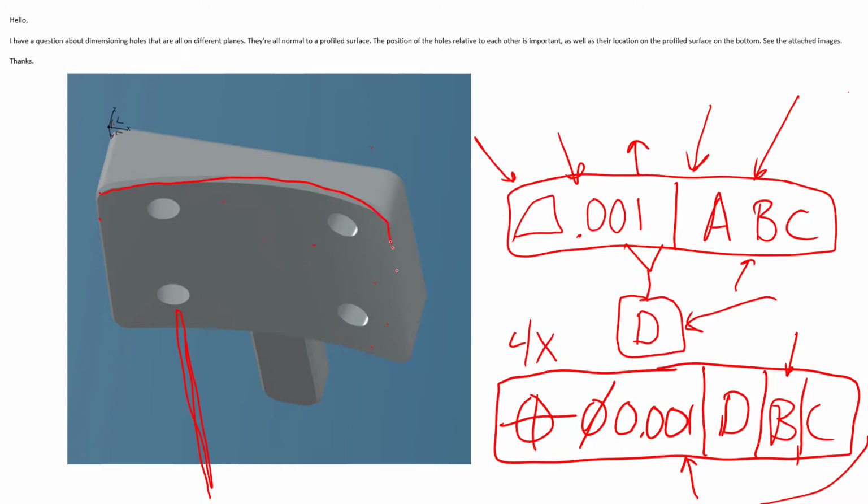This is not a very good surface to create an axis from an inspection standpoint. And the reason is, if you think about it this way, if this curve ended up being a little wider or a little bit more narrow, this axis could drastically change in location.